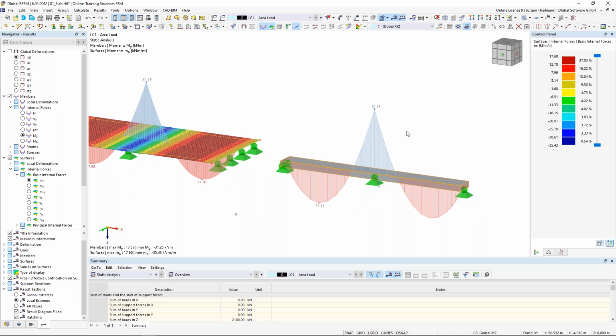So what is the reason for this? All hand calculations are built on the so-called Bernoulli beam, which is a beam theory that doesn't consider the shear stiffness of a member. And what I have now done by deactivating the shear stiffness is turning this into a Bernoulli beam. I have a small part on this in our next theory portion, but this is just a cliffhanger to keep you awake for the next theory portion.